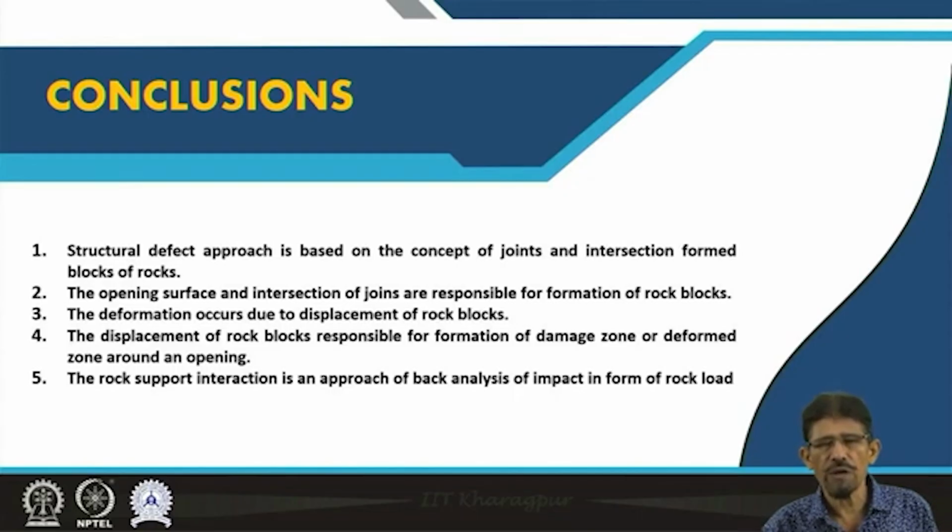although the created opening experiences tensile stresses induced along this opening. Therefore, this type of boundary is unable to sustain the induced stresses and starts moving downward into the opening under gravity. When one block moves down, another block takes the place of the previous one, and then the next covers the second block's space. In this way, the whole strata shows failure or leads to failure. In this way, the deformation of rock strata takes place due to movement of individual rigid blocks.